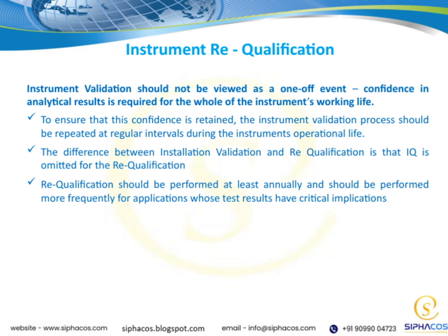Now, it's important to understand the difference between installation validation and requalification. Installation validation is typically done when the instrument is first installed, whereas requalification is performed periodically afterward, and notably, it does not include the installation qualification step. Requalification should be done at least once a year, but for applications where test results have critical implications, like in regulated environments or high-stakes testing, it's wise to perform it more frequently.